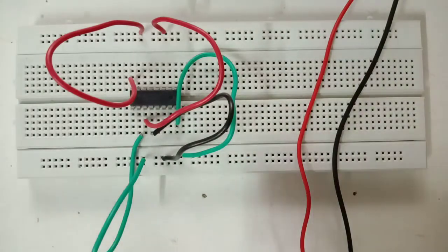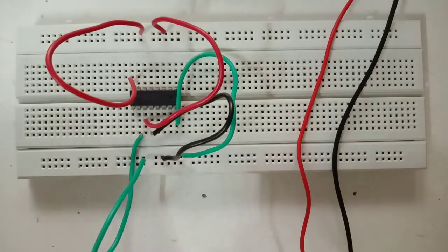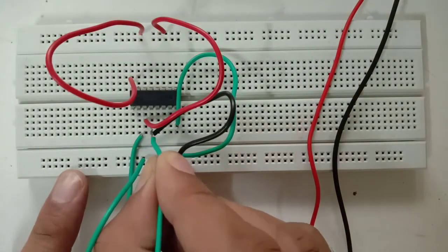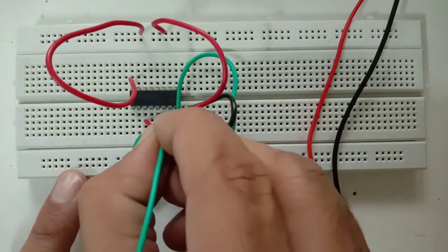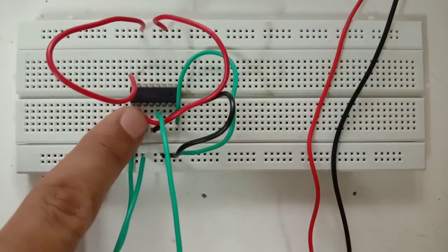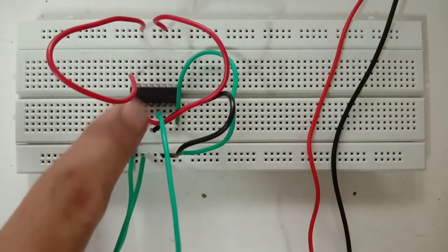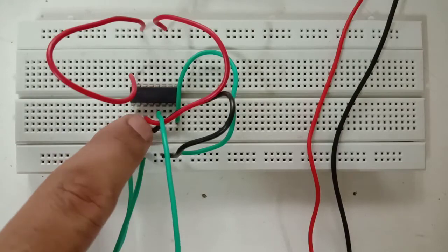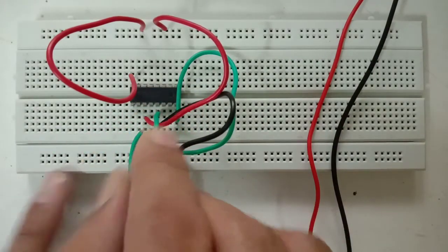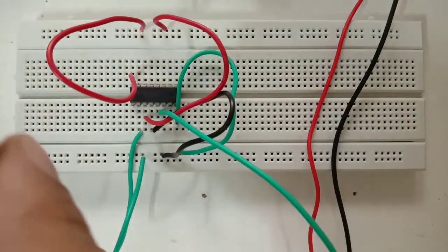Okay, so the first one is your output pin number 5, which is A greater than B. So count 1, 2, 3, 4 and 5. This one is 5, so we have connected here. Randomly you can connect one wire here, and the next wire you can connect here or here, up or down, not nearby, so there is no chance of a short circuit. So 1, 2, 3, 4, 5, it is A greater than B, this one.